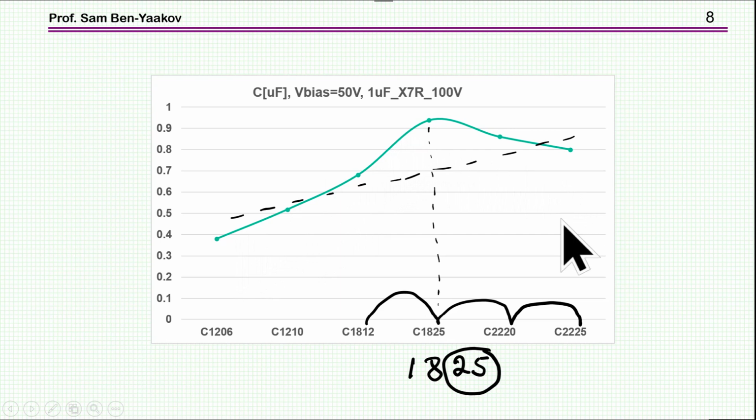One possible explanation for this dependence is the electric field that is imposed on the ferroelectric material, and it has to do with the thickness of the layer. If the thickness is smaller, then I would guess that the electric field is larger, and therefore you'll see more of a change as a function of the voltage. So here, if the width is larger, then maybe there's a change in dimension which makes the difference. So in this case, we can offer an explanation, not so in other cases.